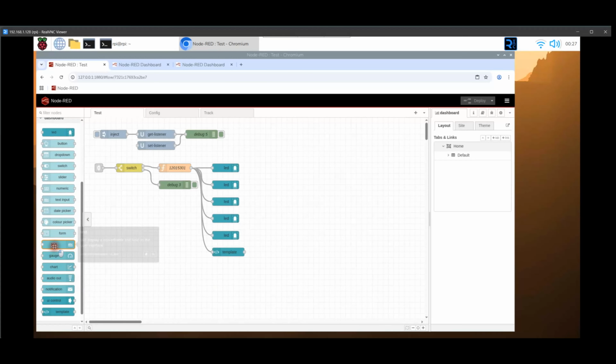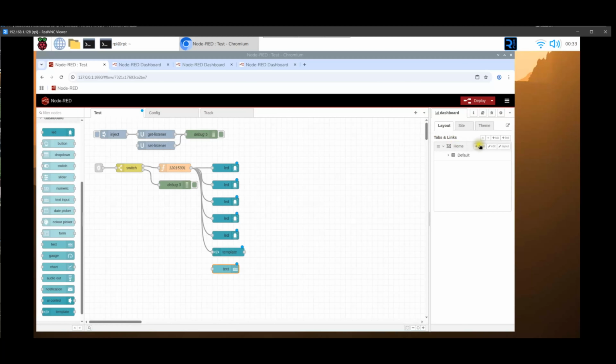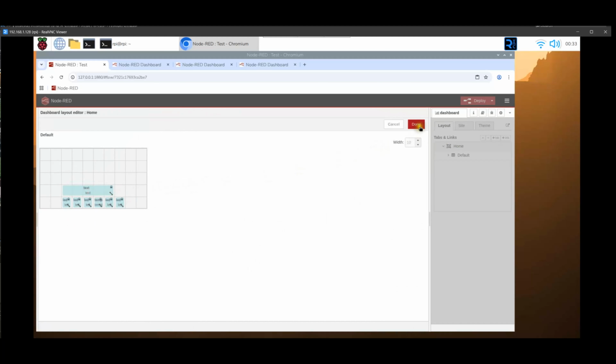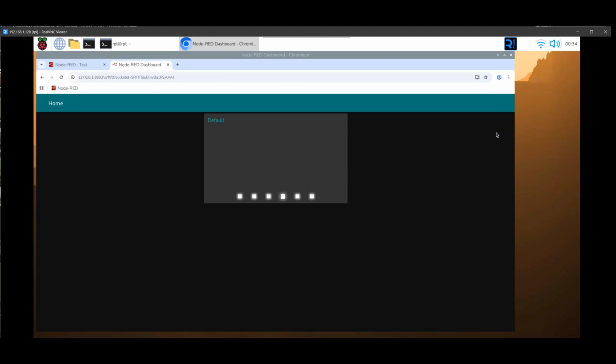The attribute set up for message.loco can be used in a similar way by dragging in a text node. When the Intercity 125 travels over a piece of track that has an RFID detector underneath it, its location is updated on the display, and the name of the locomotive detected is also shown.